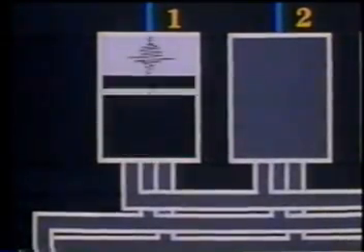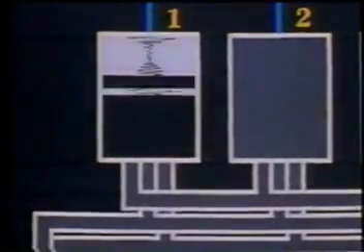This signal enters the extension channel and is sampled 12,000 times a second. In extremely slow motion, we can see that each sample of the analog signal is coded into a 12-bit digital code word. The arrangement of binary ones and zeros now represents that sample amplitude.